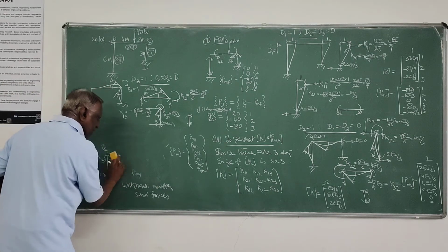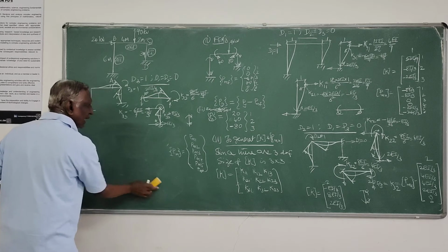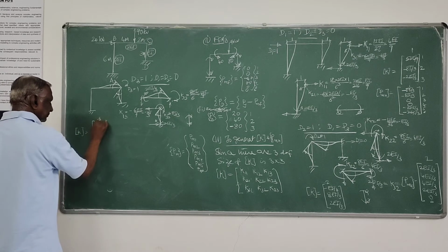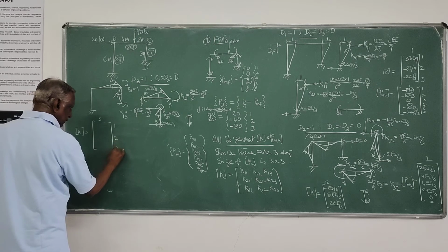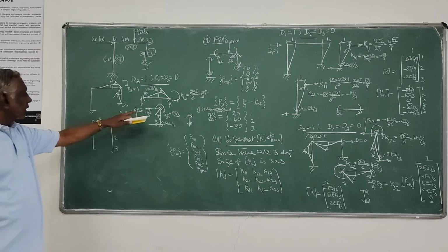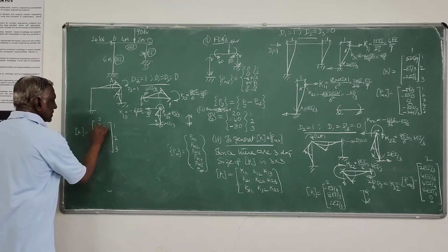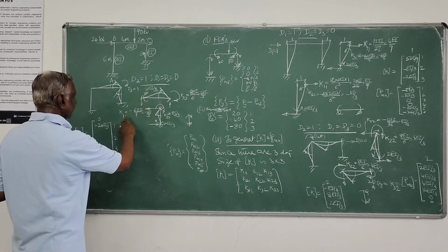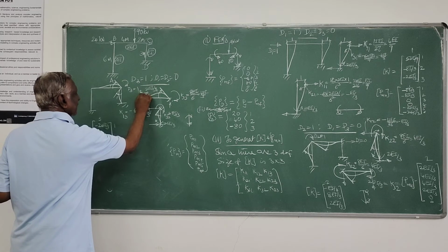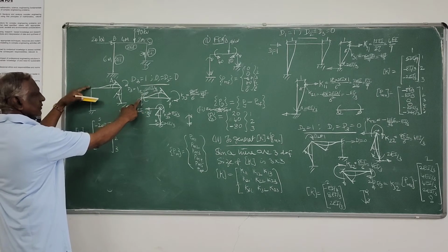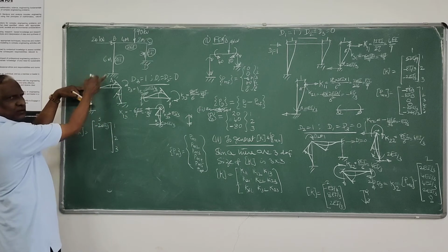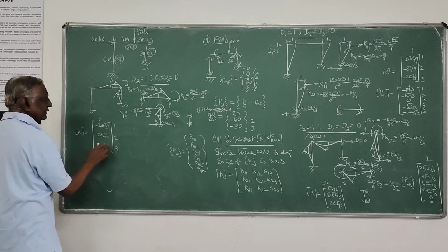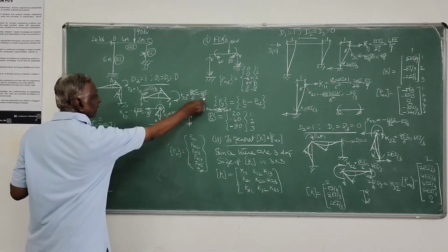Now you can type that last column of the stiffness matrix as well as the PMU matrix. So that is K. The third column corresponds to these 1, 2, 3 forces. 1, 3 I have already identified here. It is minus 2EI by 3. And 2, 3 is, here we have this is K2, so this corresponds to the second coordinate, moment 2. So it is that force that corresponds to 2EI by 3. And 3, 3 is 4EI by 3, 4EI by 3.